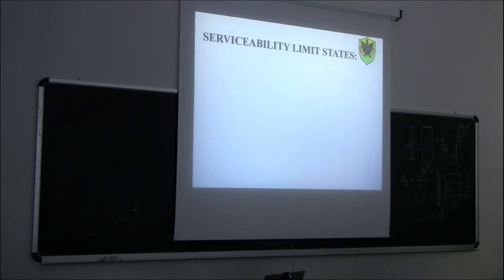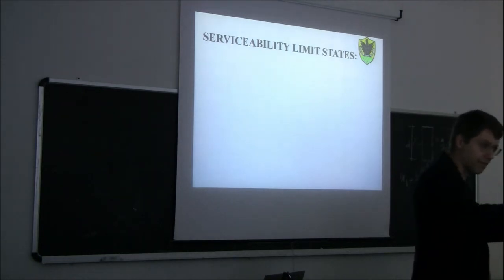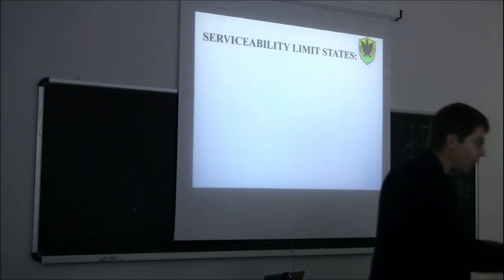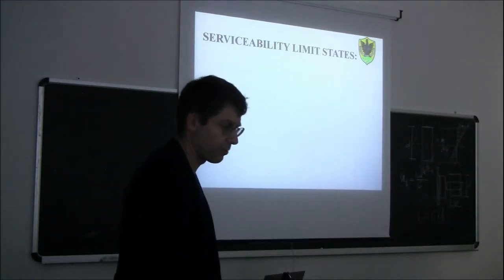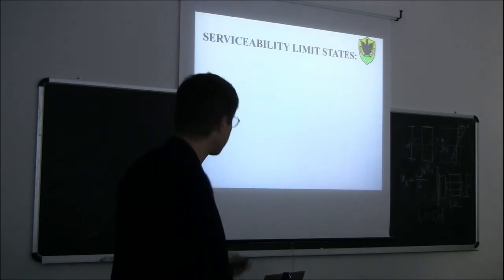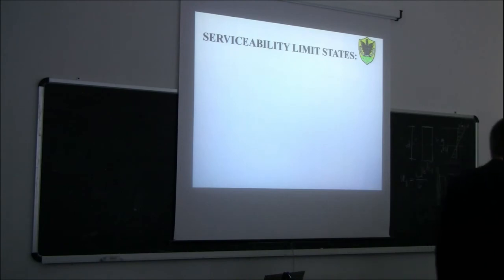So the suggestion is, after designing your beam for bending, to check immediately either the lateral torsional buckling, if your beam is long, or the serviceability. Those are the 2 to proceed with. In this case, for example, we decided to go for the serviceability states.